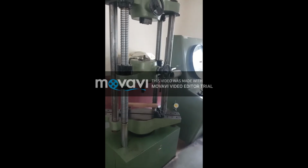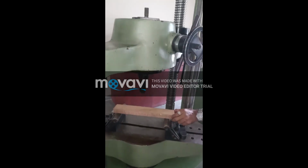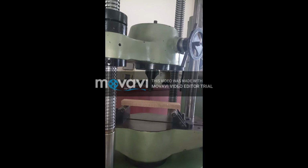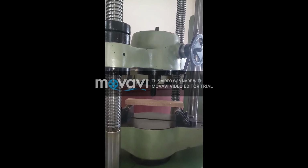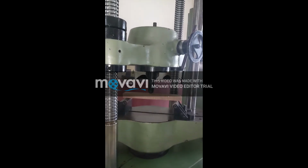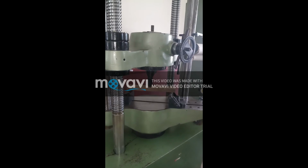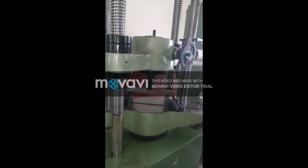So this is the UTM machine. First we fix the specimen, the bending specimen. We commonly use wood as the bending specimen. The wood specimen is fixed in this manner, looking like a simply supported beam condition. You can observe the central point load acting at the center. Also observe the center distance from one roller to the other roller, which is the small l we use in the deflection formula.